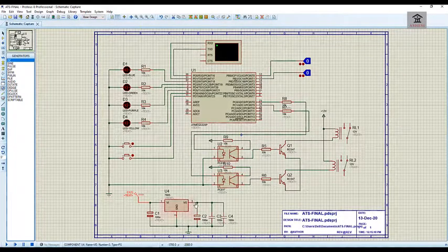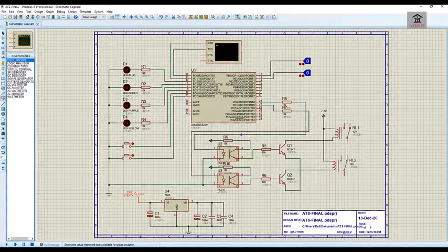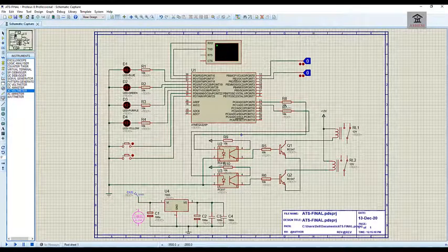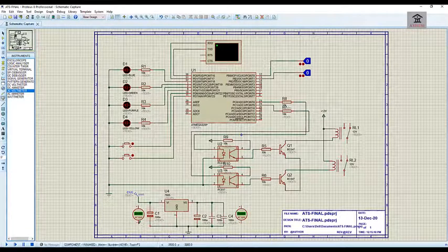And then I'll now go into instrument mode, look for a DC voltmeter, and then measure what is at the input, and then measure what is also coming from the output. So I'll connect the voltage meters like this, and then like that. And then from here, like this.